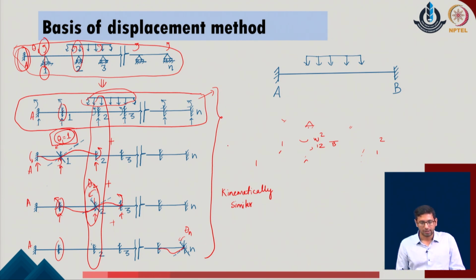So, what we have is that all these systems together are kinematically similar to the original problem, but we have not verified in this case whether the conditions of the forces which are net available at this given joint, in the direction of the given rotations, are also being followed with respect to the original problem. That gives us the conditions of static equilibrium, and we make these systems statically similar. So, kinematically the systems are similar, but statically the systems are not similar.